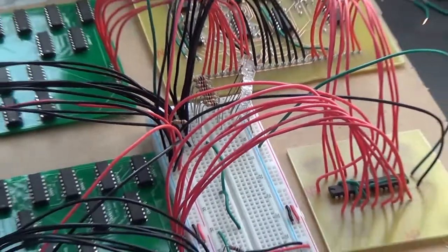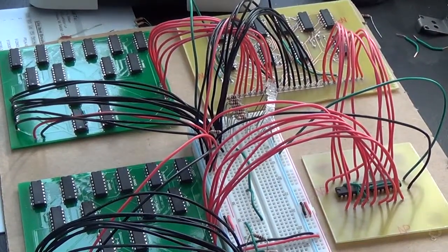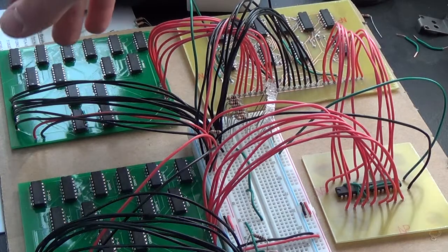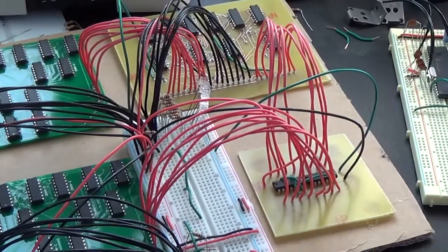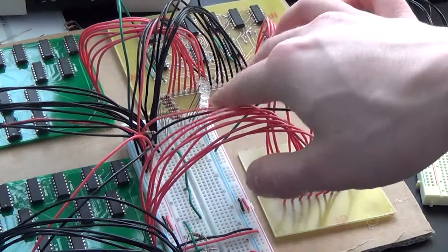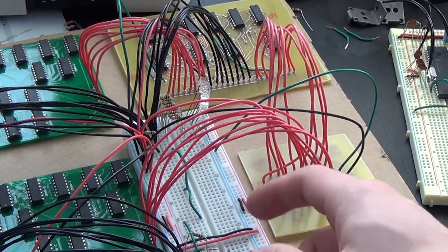And the A register at this point is probably all high, because a value of 255 plus 1 will show 0 on the 8 bits visible, because that would cause an overflow into the 9th bit, which we don't worry about.